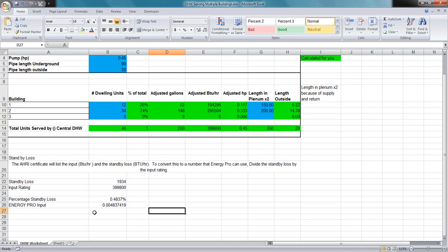If you have a boiler with a tank, the boiler system is going to be rated on the recovery efficiency that's given by the nameplate or by the HRI Directory, and the standby loss is for the tank. That's accurate, and that kind of logically follows where you're generating all of the heat in the boiler system, so that's going to have an efficiency of generation, or an efficiency of how quickly or how efficiently the gas energy is converted into heat